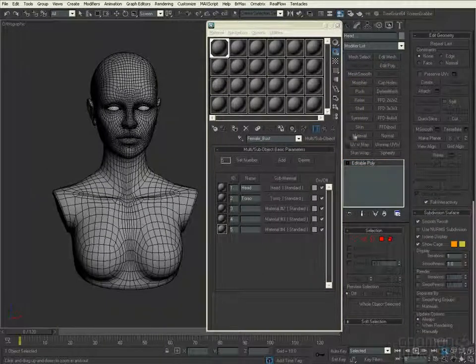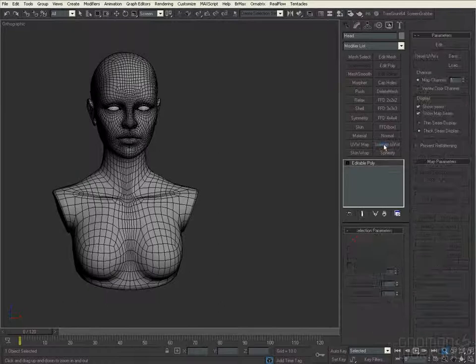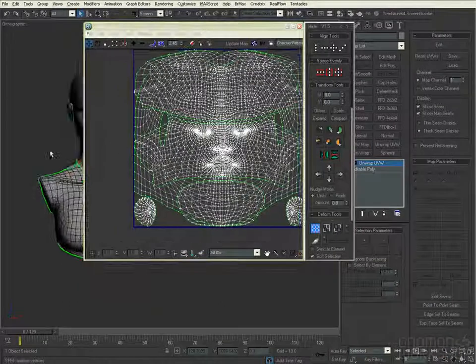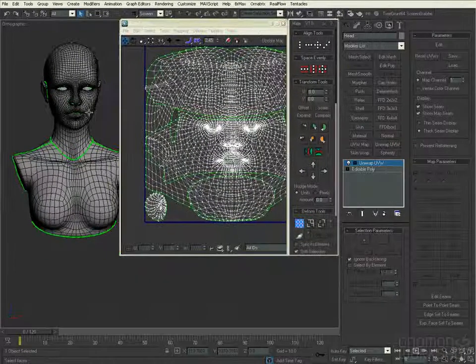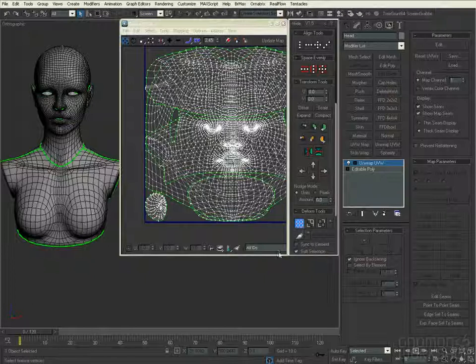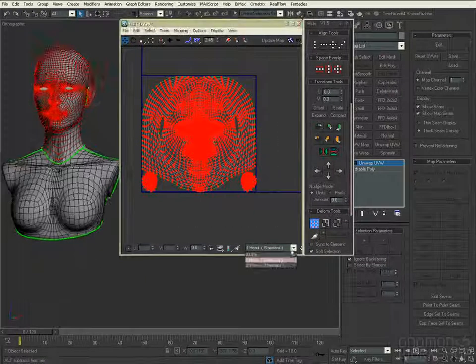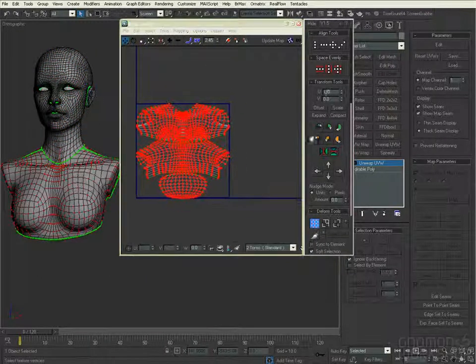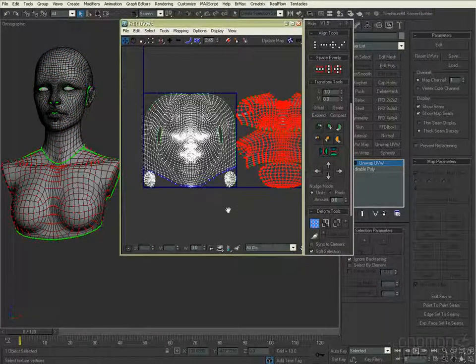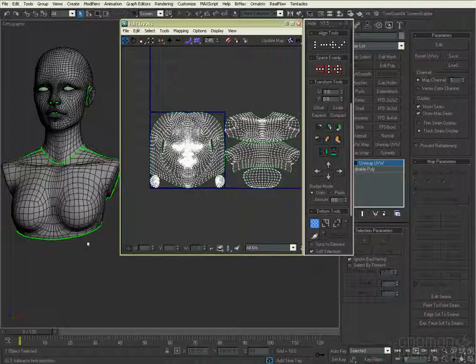When you open up the Unwrap UV page, you will see everything all meshed in together, overlapping. But there's a section on the drop-down menu at the bottom. You select 1 and just keep 1 in its own place, and for 2, offset the U direction by 1. So now you have a model ready, UV ready for ZBrush and BodyPaint.